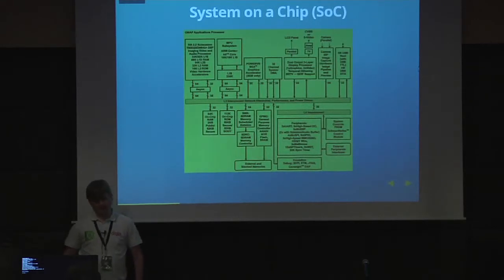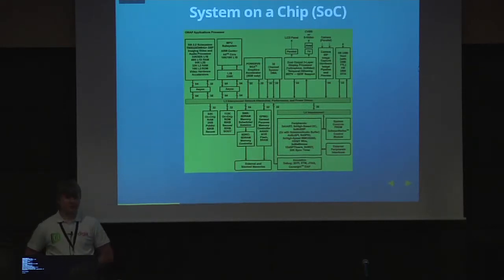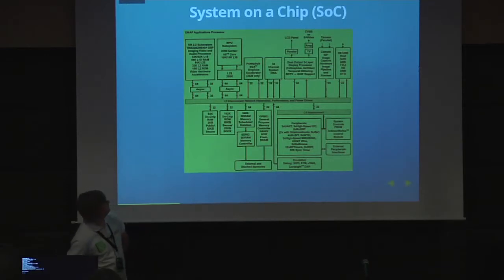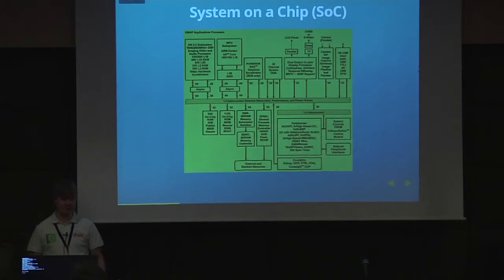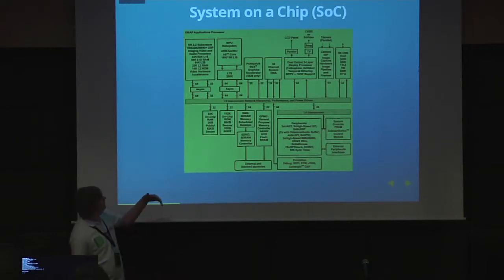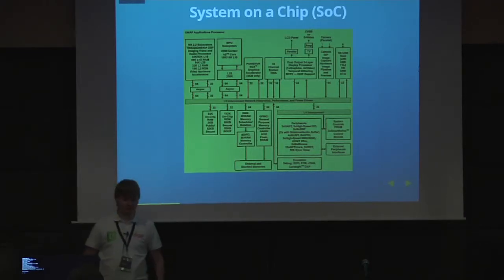And as I previously mentioned, these CPUs don't typically exist alone. They typically come in what's called a system on a chip. I guess this is not too terribly important to understand, but this is actually the chip from the BeagleBoard. I think it's TI OMAP 3530, something very, very close to that. And you can see it has, on the actual die, both the CPU, the DSP, and the PowerVR SGX graphics accelerator.